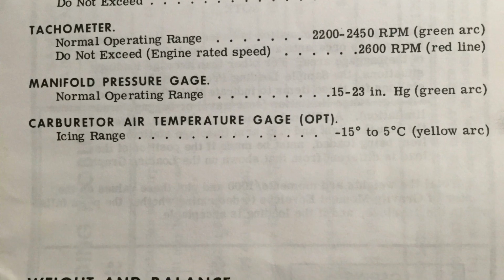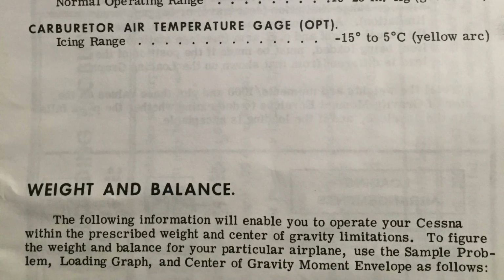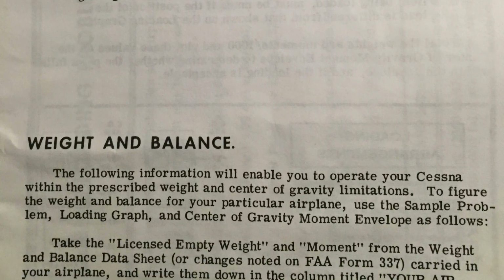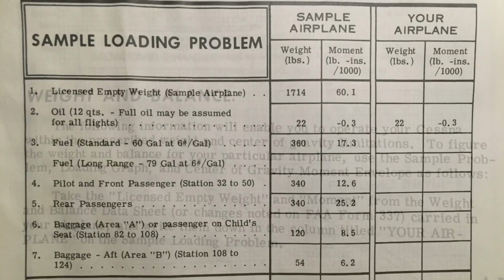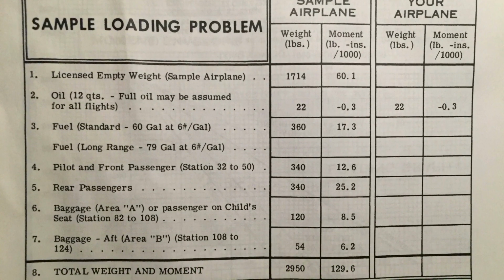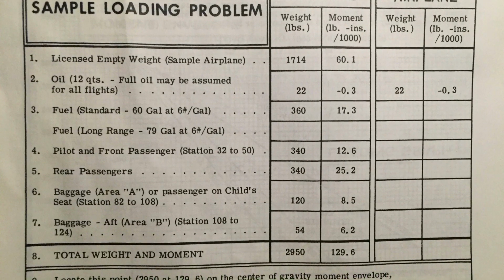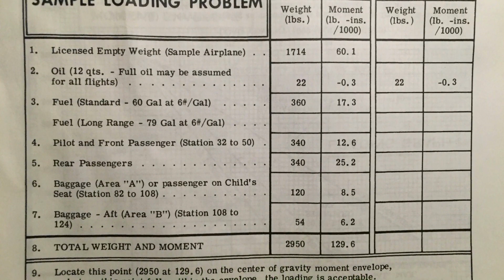At the bottom of this page, you will notice it begins the weight and balance section. So take a few minutes and look at this section on weight and balance, and go ahead and put together, just scratch out on a scratch pad, a rough weight and balance. I'm about 225 pounds. So do a weight and balance, and let's kind of have a feel for that.